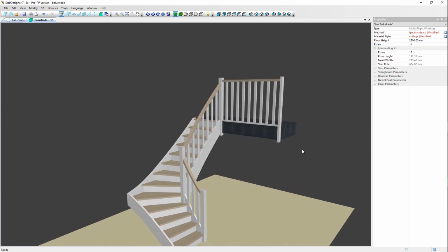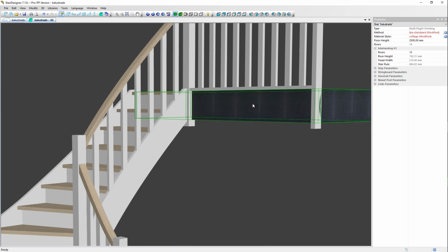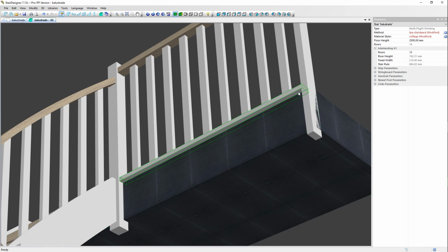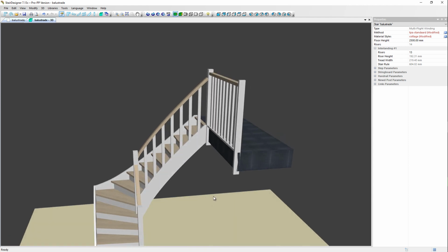Now we are going to do some finishing parts. Let's say, for example, that the front of this arrival floor is not finished and that this needs to be covered with a board. This setup makes it possible because you have the possibility to put a groove inside of that lower rail and also on the side of your newels, so that you can enclose here a covering plate. How do we create a covering plate? We're going back to the 2D.